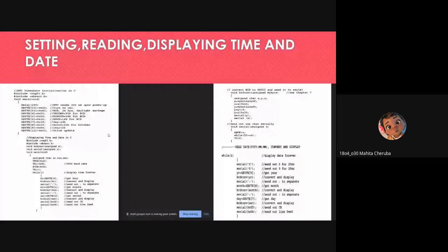So first thing is we are initializing with unsigned char as character, and we are using TMOD of 0x20, and the second thing is the baud rate. We are giving the baud rate value, and then we are going for the SCON, and then we are using timer 1 because we know if it is 0x20, we can say that it is timer 1 mode 2.